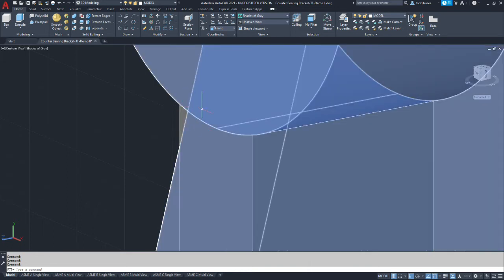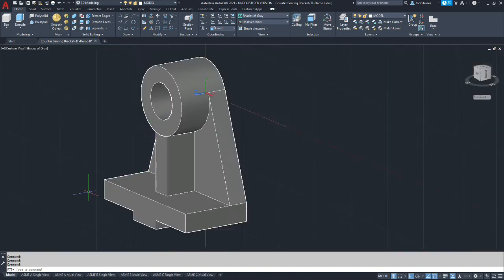So this little area where the straight line is going to get filled in, and we'll have to cut that material back out. But that is similar to how this process would have been manufactured. Typically this would have been a casting with fillets all around, and anything that has a square edge on the end has been machined from a larger piece.